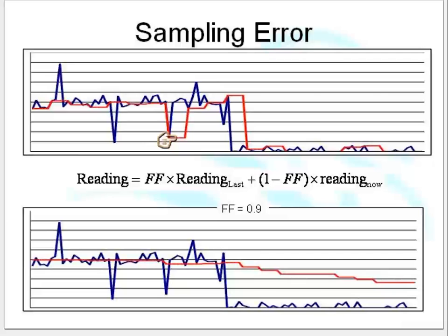That is plenty long enough for it to have outputted to a valve. And if it sees a bad reading and outputs to a valve, then the valve will make the system go into oscillation, which means that the whole thing goes silly. Because once we're in oscillation, it's very, very hard to get back out.